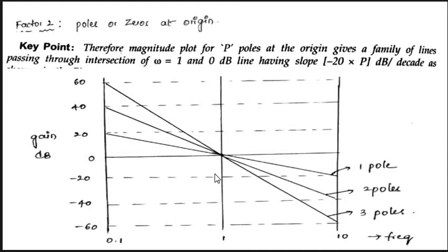So where do we have to start this one? At 60 dB, and it decreases by 60 per decade, so 60 minus 60 is 0. The line is drawn like this, and again from 0 to minus 60, the line is drawn like this. For one more decade, we start at minus 60 and go minus 60 minus 60, that is minus 120 dB, and like that the line will be drawn.